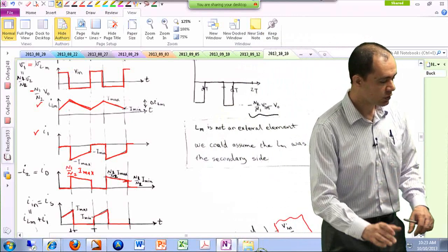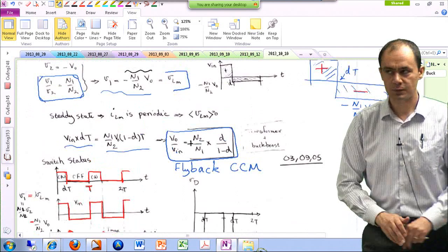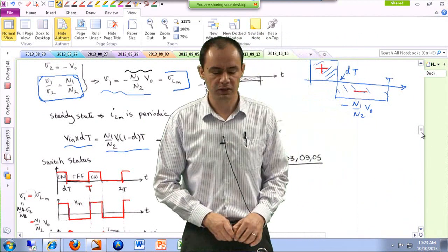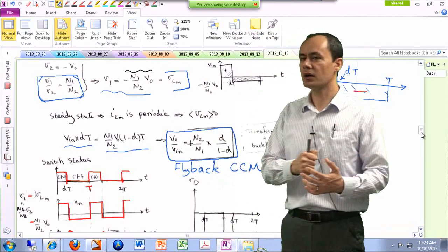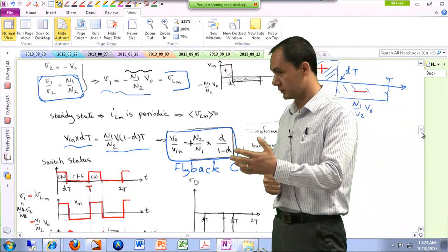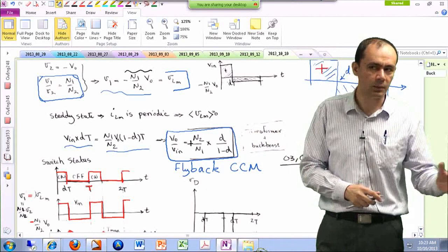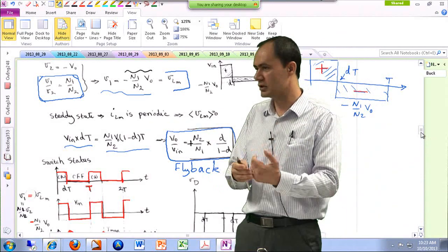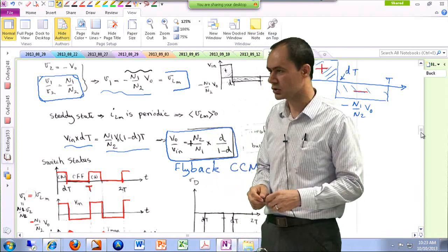Well, in that particular topology, you're right, because in the full wave rectifier with a center tap, you are trying to avoid using 4 diodes and only use 2 diodes. Therefore, the voltage stress across those 2 diodes is doubled. So you're kind of tricking over here. That is not really comparable, because in this topology you're only using 1 diode. So the voltage that we calculated is stressed over this one particular diode.